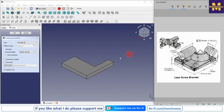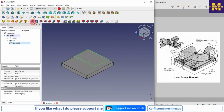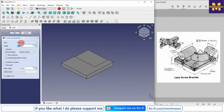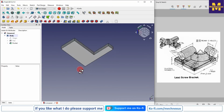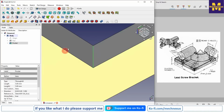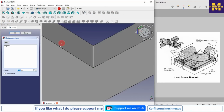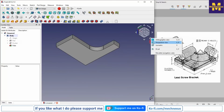So I will remove the material and say through all, say OK. Now I will select this edge and click on the fillet icon, and I will give my fillet 45, say OK. Now switch to the isometric view.